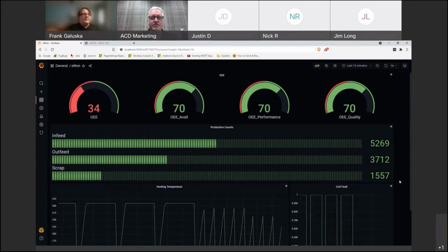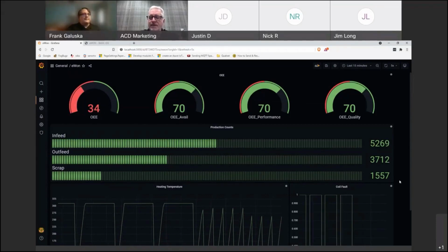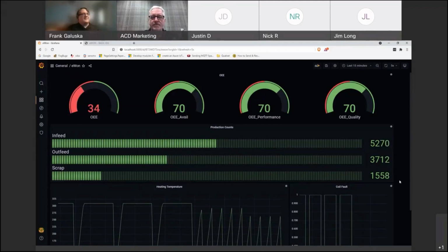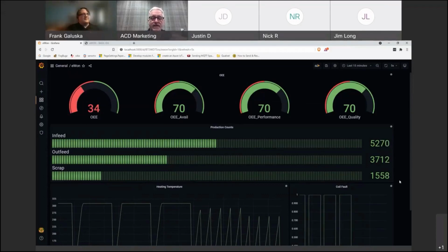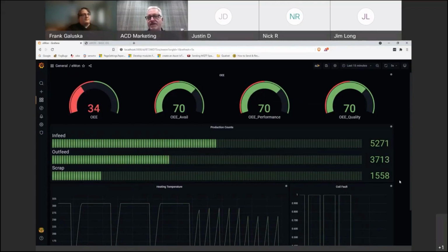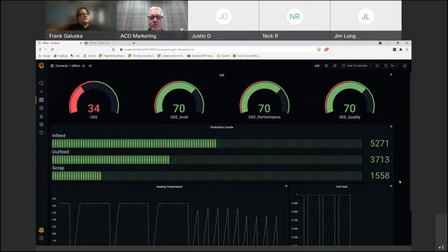So we've essentially shown, outside of my extra talking there for a couple of minutes, that it took us only 10 minutes from the start of your conversation to now to say, here's how you can set up data from a Siemens PLC as an example into an Ewon Flexy, get the data up to a data broker, and then into a visualization tool. A little bit more work to set those tools up, et cetera. It's not only just 10 minutes, but